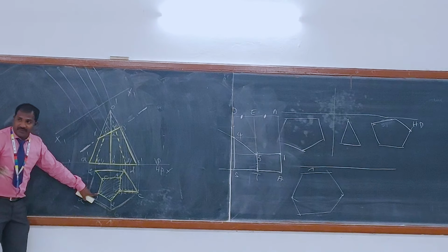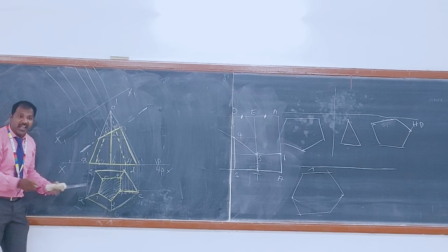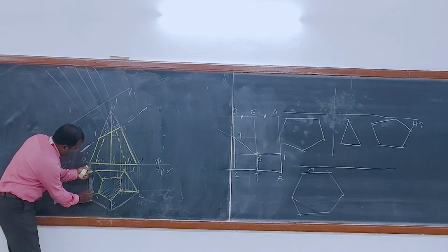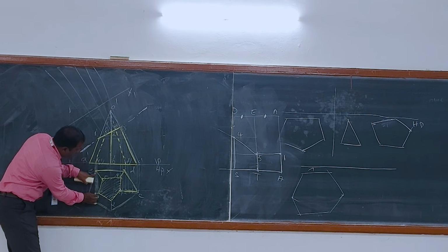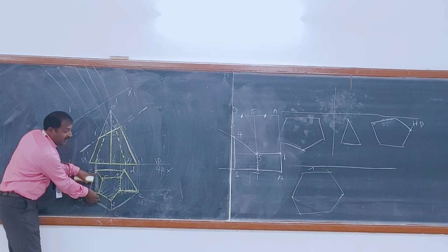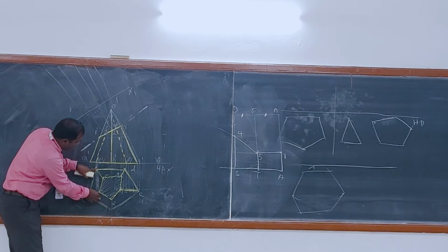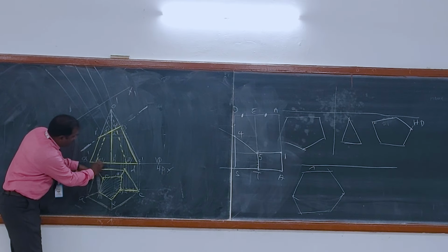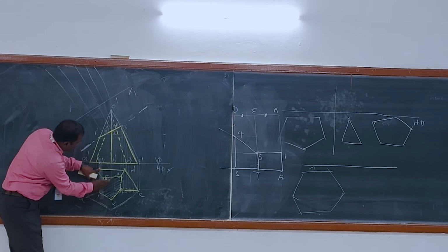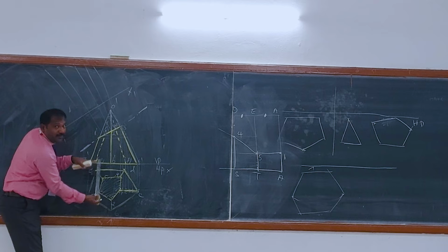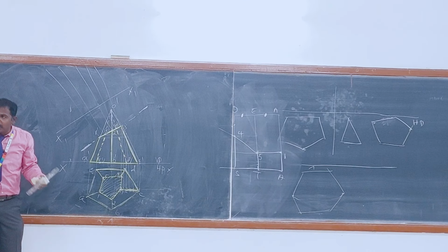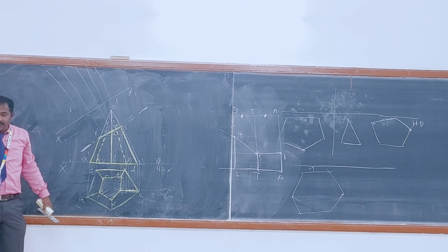You did not draw the vertical line here. You have to move the scale and draw a vertical line for each point. We have to measure vertically, don't forget, because we are drawing the arc, the vertical line was not drawn. You have to measure from here only. Measure the vertical distance, the 90-degree distance. Clear?